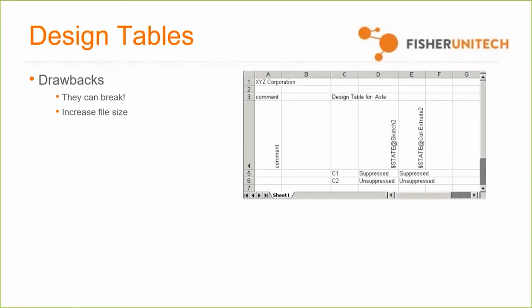Also, it can increase file size because imagine it, you get really happy that you've got a nice design table and you make 150, 200 configurations of a component that all have complex calculations going on, and then it brings things down to a screaming halt, or they just don't go as far as you want.